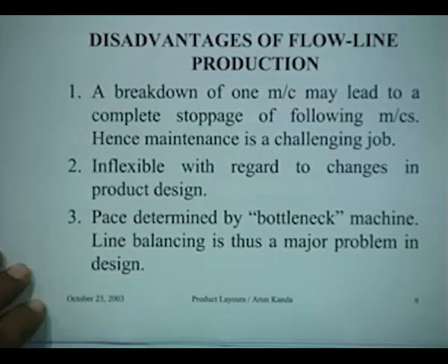Obviously, if different operations, workstations take different amounts of time to process the part, the overall pace of the line will be determined by the slowest machine, and therefore you would like to have, as far as possible, fairly constant times for all the workstations. This may not be possible for various reasons, but at least that's the intention.